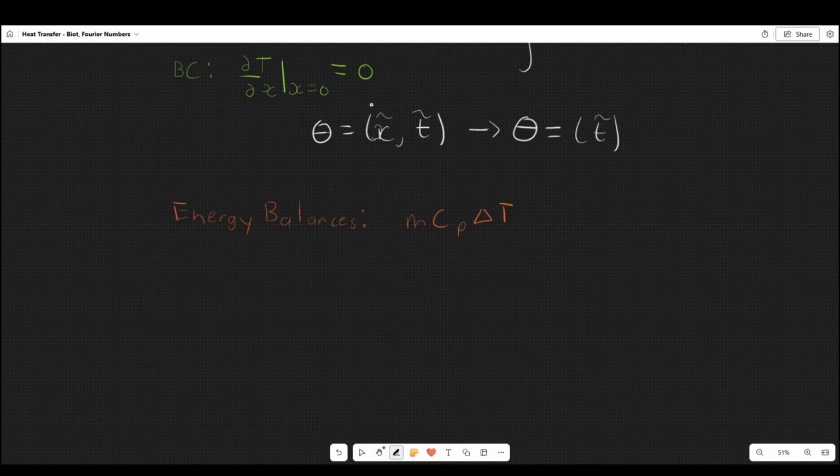This basically summarizes the amount of heat that was generated or lost. And so this must equal the convective term. So this must equal h, the negative version, right? Because whatever goes in must come out and they're opposite sign. T minus T infinity. Perfect.